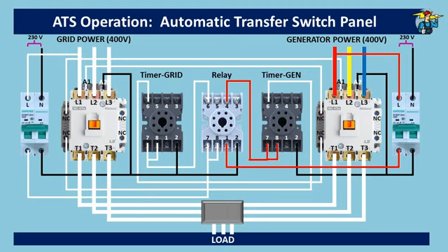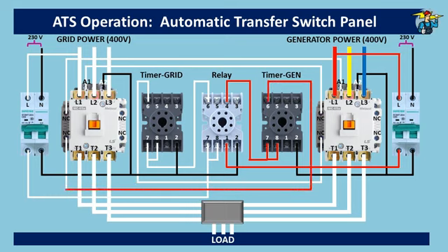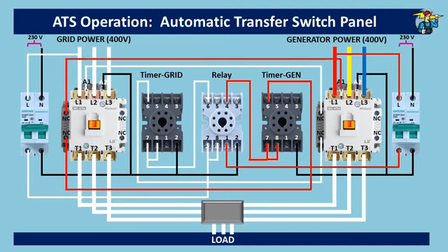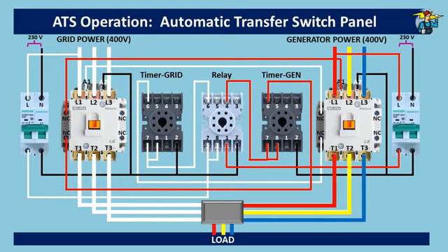Although the relay is powerless yet, the generator timer is powered now, and after the set delay time on it, number 6 also gets power, thus allowing connection to the A1 of the generator contactor. This connection too goes through the normally closed auxiliary contact of the grid power contactor to make sure it is at off position. This allows the generator contactor to go to on position, and the load gets 3-phase power through the generator now, and will run like this till grid power is restored.